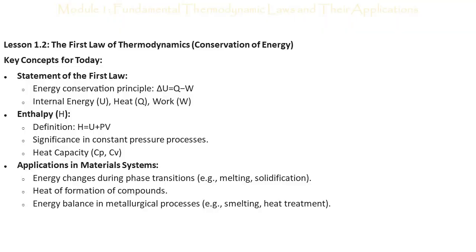Let's get straight to the heart of it. The first law of thermodynamics can be stated in many ways, but for a closed system, it's most commonly expressed as delta U equals Q minus W. Let's unpack this equation. Delta U represents the change in the internal energy of the system.